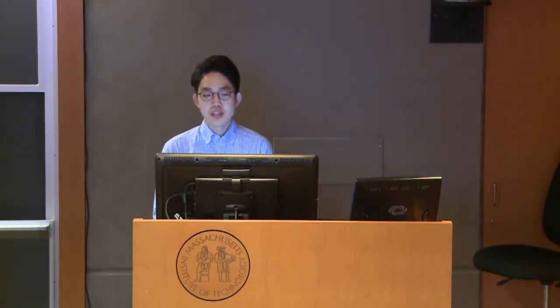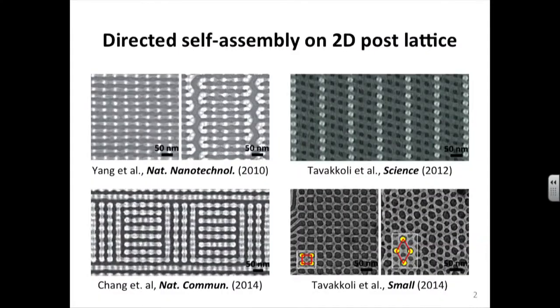In our group, we have been studying graphoepitaxy of PS-PDMS on 2D post-lattice templates fabricated by high-resolution E-beam lithography. We have previously demonstrated complex circuit-relevant patterns using PDMS functionalized HSQ posts as shown on the left. Using PS functionalized HSQ posts or sacrificial PMMA posts, we have demonstrated three-dimensional bilayer mesh structures and whole arrays with different shapes and geometries as shown on the right.